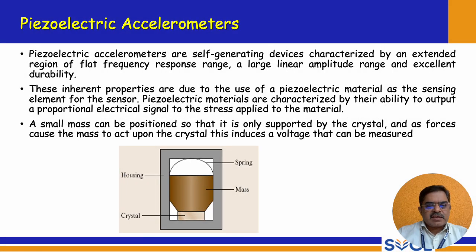So piezoelectric class accelerometer, we will see one example here. Piezoelectric accelerometers are self-generating devices characterized by an extended region of flat frequency response range, a large linear amplitude range, and excellent durability. So that is piezoelectric accelerometer, and these inherent properties are due to the use of piezoelectric material as the sensing element. So piezoelectric crystals can be used as sensing materials here.